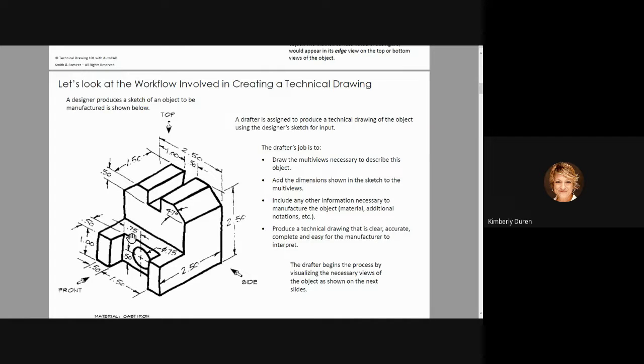So to me, it would be better. And if I wanted to put 3 views, it's fine. I will not draw any view and not have a size or location notation in it. If it's all too cluttered in just one view, I'm going to spread those around to other views. But just remember, you cannot dimension things that you can't touch. All right, so no hidden line dimensions, or size notations.